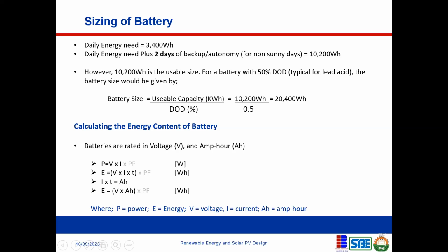During the load details, we've already applied the power factor. That is why you will not apply it here: the load is not taken directly from the battery. The load is taken from the inverter, and the inverter is not a load that has those. You are feeding DC current to it, so you don't need power factor at this stage.